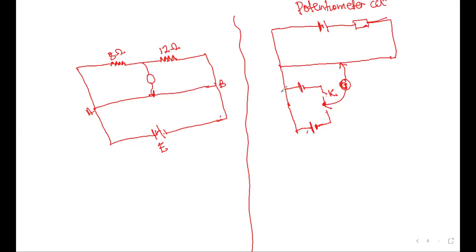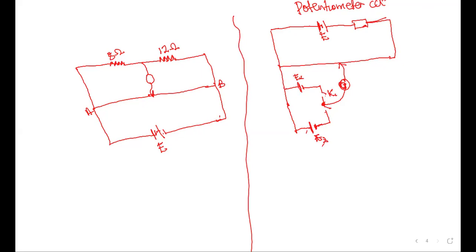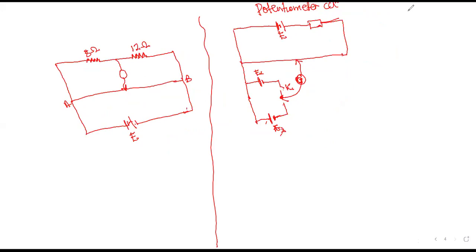So the meter bridge, and the potentiometer circuit. We use the Wheatstone bridge circuit, whose practical application is the meter bridge. We use it to compare resistances of resistors and also to determine the resistance of an unknown resistor.